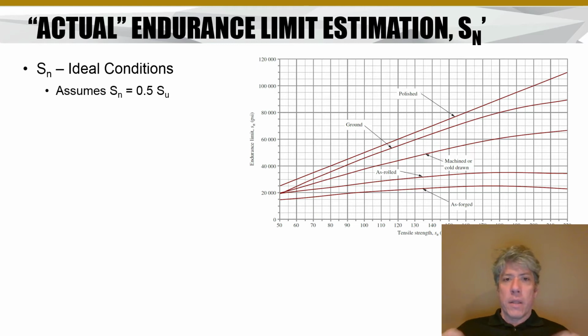Now when these tests are performed, they're performed under ideal conditions. So the stress and life relationship that you get from them is very idealized. It doesn't represent real world behavior of the material. And so things that can go wrong are things like, well, surface finish. If there's not a perfect surface finish like this polished sample we're talking about, well then the part simply will